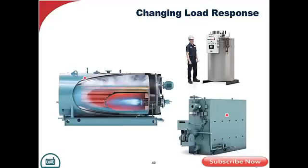But don't ever forget that these bigger boilers that you might already have and have invested a lot of money in, and you've added controls and burners and so on, can do real well too if they're properly controlled and programmed, so that once they come up to pressure, they can respond pretty good. Now, I will say that water tube boilers innately will respond much better than a fire tube will to what I would call swing loads, varying loads, because they don't have as much mass. They can respond very, very well. But that doesn't mean that you throw something like this out. It depends upon that load, what you have, and what might be done to it to make it respond better.